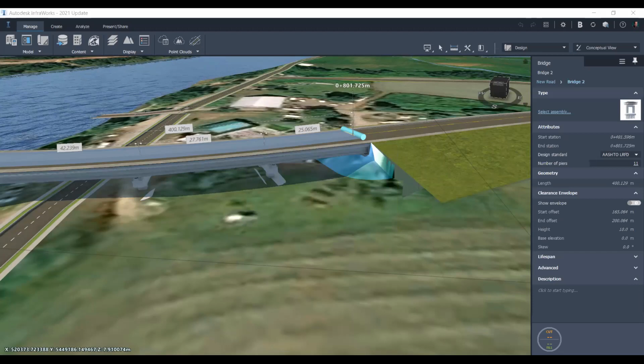Now, these three files can be used in either Civil 3D or Revit. And again, they're dynamic. So after I bring it into Civil 3D, if the InfraWorks user changes the bridge, they update this file and I reload it, again, sort of like an XREF, into Civil 3D.